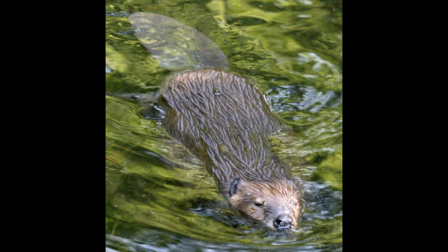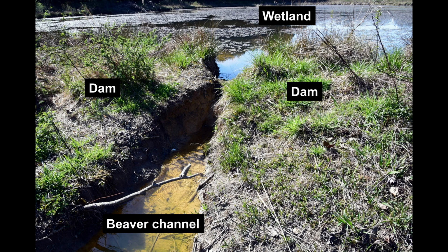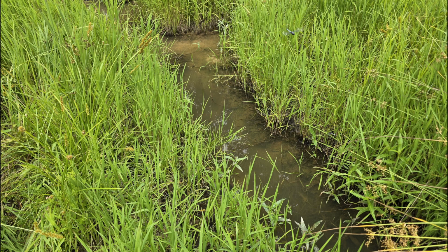Beaver often move into constructed wetlands and ponds and can be expected to quickly modify the dam, spillway, and the water control structure. Here is where beaver have dug a channel through the dam of a constructed wetland. The channel is draining the wetland just like somebody dug a ditch through the dam. Here's another channel that beaver dug through the top of a dam.